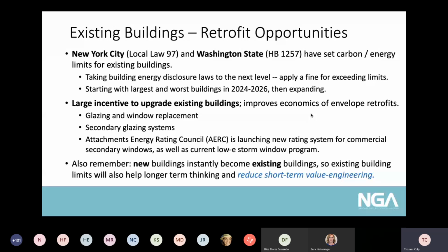The whole point of it is to allow ultimate flexibility for the building owner, architect and designer, but that does also mean they can make trade-offs. And so we have heard that in California, that people do that. They will put in a little better insulation, or a little better lighting system, and they'll use that credit to value engineer and take out a spacer, or take out the argon, or a thermally broken frame.